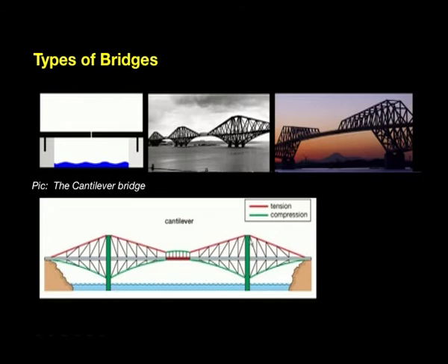These pylons are a purely compression member, and these bottom arms again have compression because there is load acting on either ends. So, these are on compression. These top arms are on tension because there is load acting on ends. In all the cantilever, it is always such a way that there is tension in the bottom and compression on the top. So, this little part is cantilevered from these two portions.